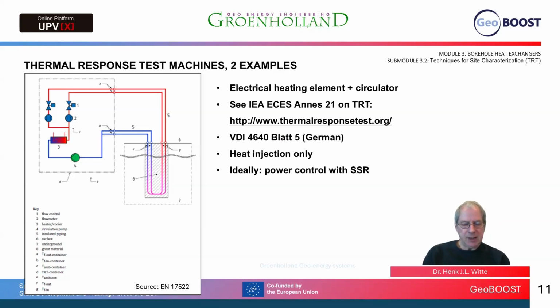There's a lot of information in the International Energy Agency ECES Energy Conservation through Energy Storage Annex 21 on thermal response testing. The link is indicated here. And also the German guideline for engineers, the VDI number 4640, Volume 5 gives information on thermal response testing. Those are all for heat injection only. And in the ideal case, you will have a power control with a solid state relay.